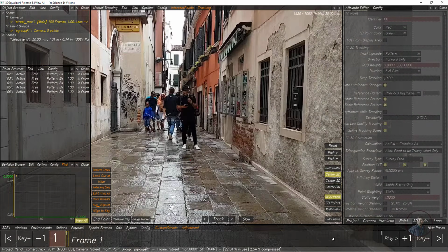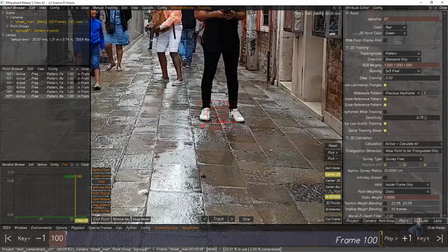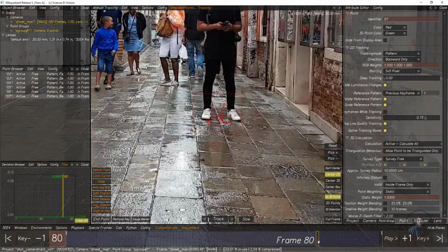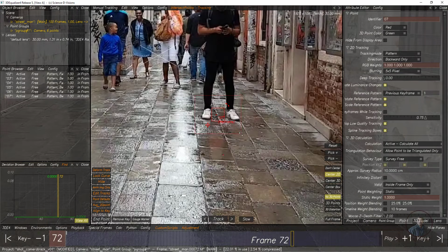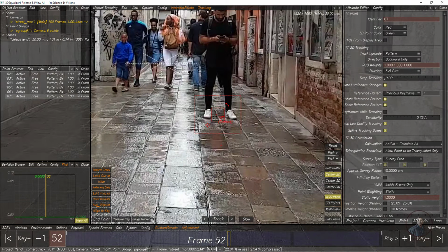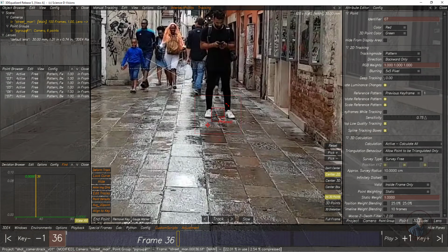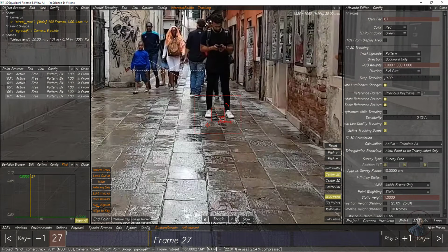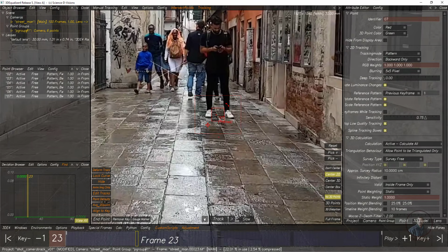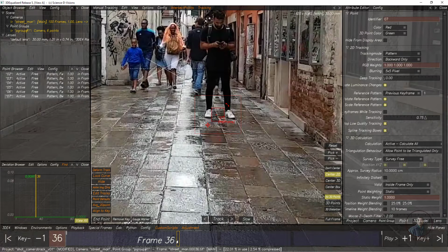Now the next point, I am going to create at these character positions here. These are again important points. At this position, simply click on this gauge marker. So this will create a keyframe. So you can see this one here. Now again we have to click on this track. Then again if you want to click this gauge marker, this will again create a keyframe. Now you can track all frames. And now suppose, guys, if you want to clear all these tracked frames with keyframes, what can we do?